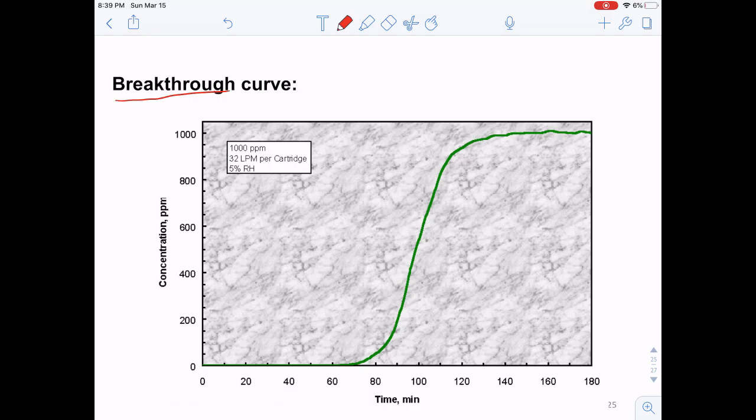So as you can see here, it is showing the adsorption process for removing certain chemicals from the water. And you can see that in the beginning, the concentrations of these chemicals are close to zero, right? This means that adsorption is happening in a very efficient way. But after a longer period of operation, the concentration of these chemicals will increase and even go to the saturated concentration. And this means that the adsorption is not effective under this situation.